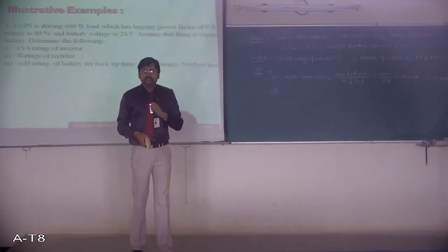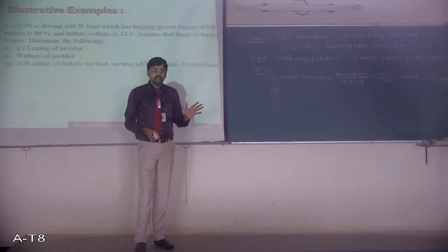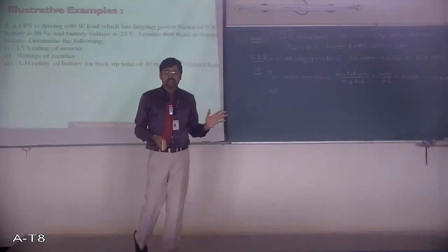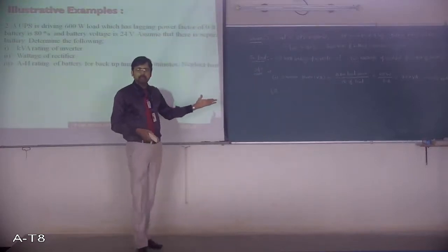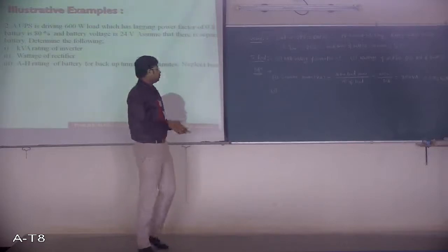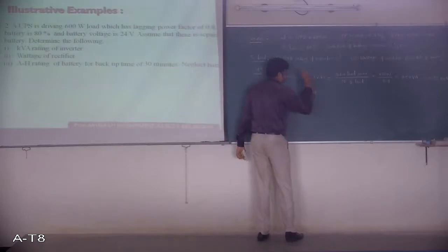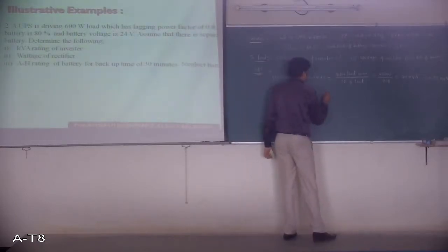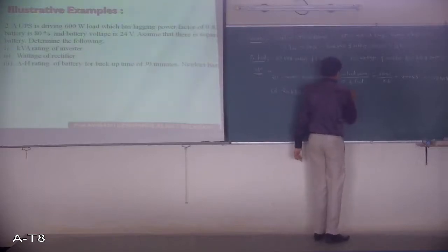By how much? 20%. But remember, the rectifier output is DC. So you have to calculate the power of the rectifier in terms of watts, not in terms of VA, because it converts AC to DC. So the rectifier output can be calculated as inverter output or inverter power, which is nothing but apparent power.